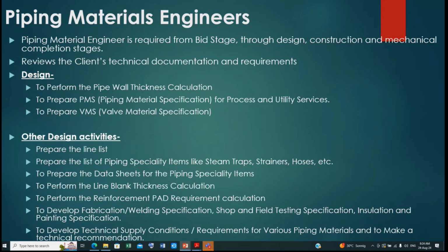It has to be calculated as per ASME B31.3. And that's why, as a piping material engineer, we have to do the calculations to arrive at the thickness of this line blank.